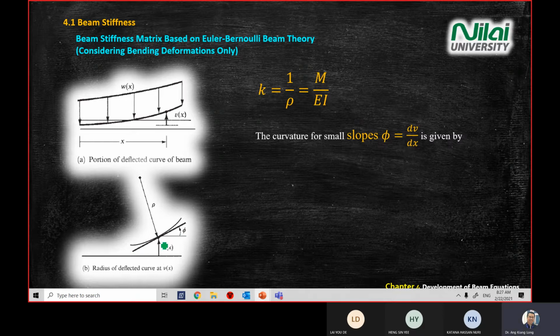How you find this line is the vertical displacement and the curvature of your object, of your tube or your beam here with the R. So the definition for the slope, or gradient, is given by the differential of your vertical displacement, dv over dx.